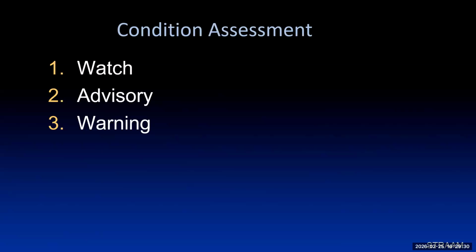So the condition assessment. Now, this is the way that new standards are going: instead of suddenly saying it's not safe, there will be watch, advisory, and warning. So you're gradually going up to the level at which you really need something doing. Watch is all right. It's basically okay for the moment. Advisory will be, we can see something. You need some maintenance doing in that area. Don't just paint over it. It needs something doing. And three, a warning. If you don't do something, you're going to have a problem.